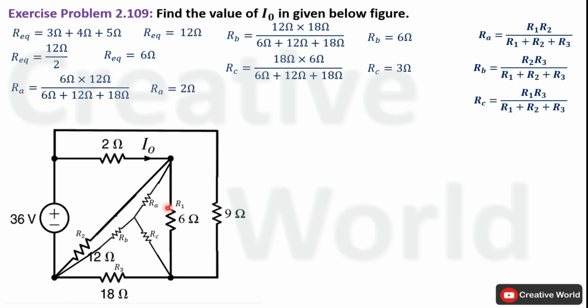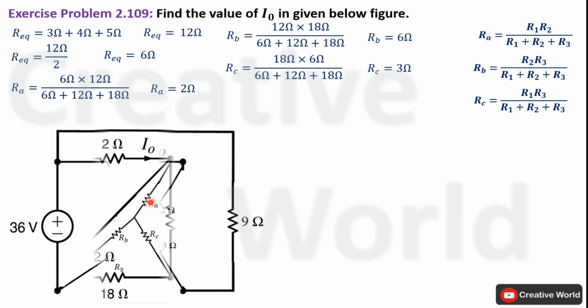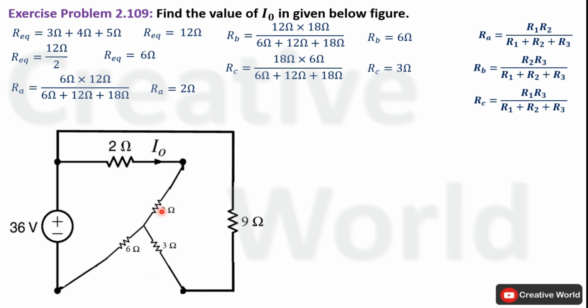Now we have the values of star connection. This star connection is equivalent to this delta connection. So we can replace delta connection with star connection. Modify the circuit diagram by indicating resistances of star connection. At this stage, these two resistances and these two resistances are converted into simple series network. So we will find their equivalent resistances.